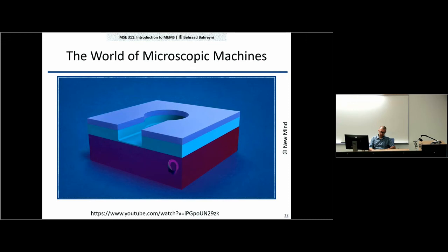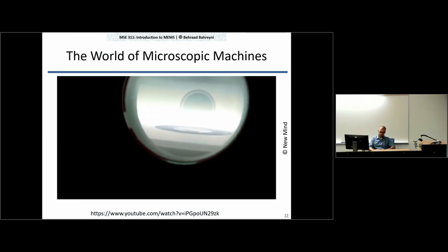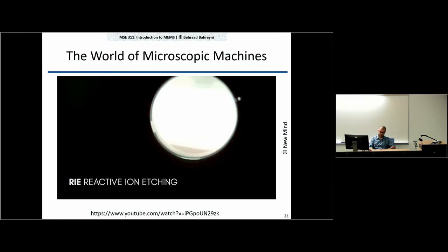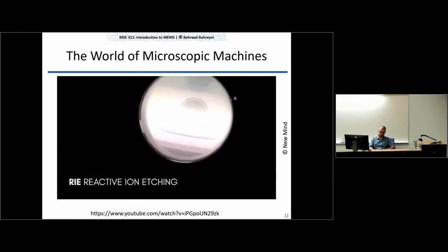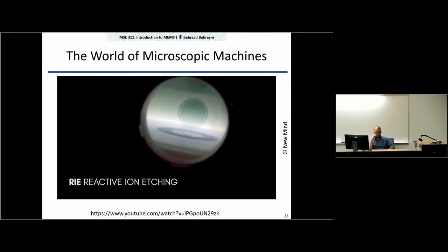The etch resistance of the substrate can also be controlled by selectively bombarding it with atoms of boron in intermediate steps, using traditional photolithographic techniques. While traditional wet chemical etchant can be used, a more common approach is the use of a reactive gas driven into a plasma state via radiofrequency energy in an etching process known as reactive ion etching.